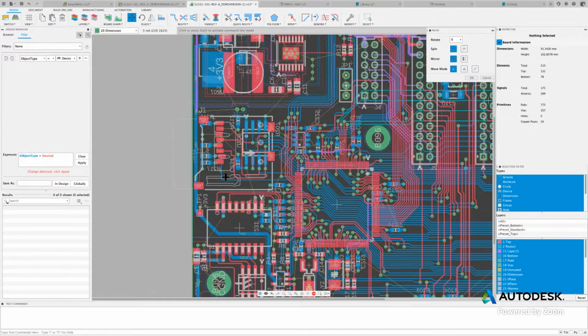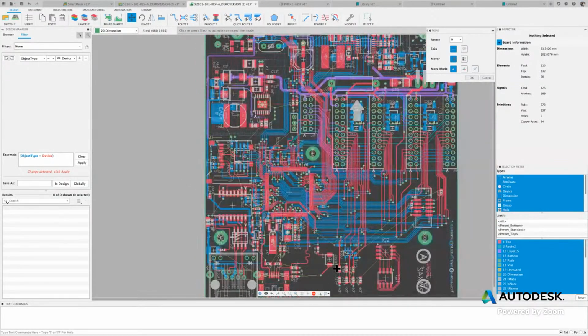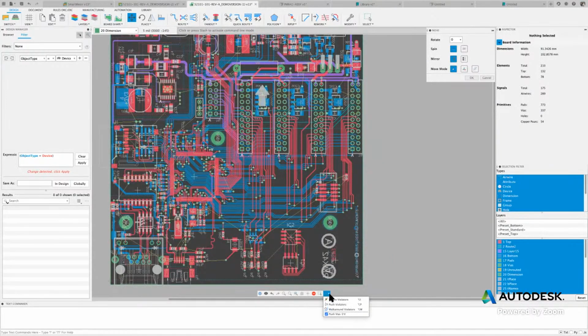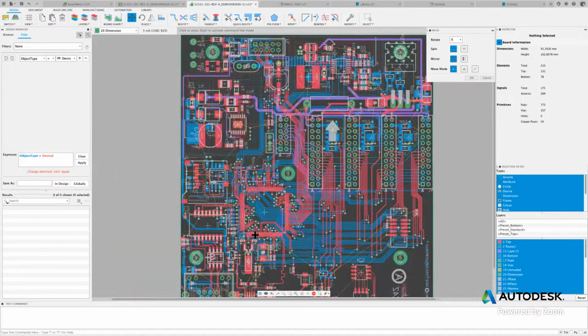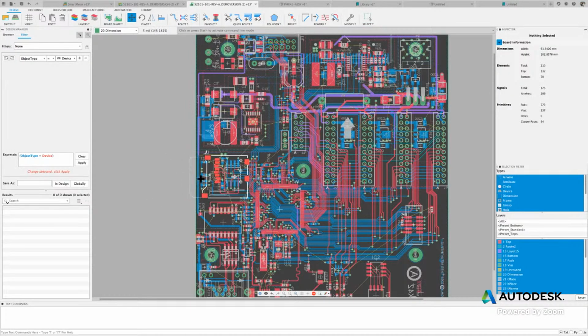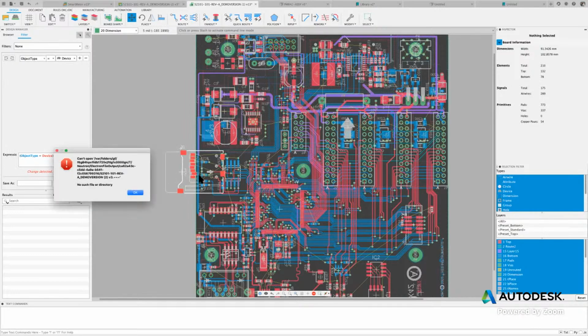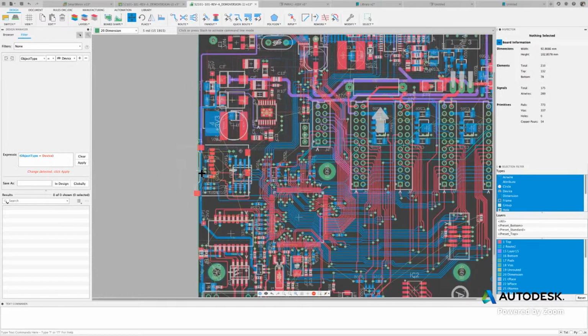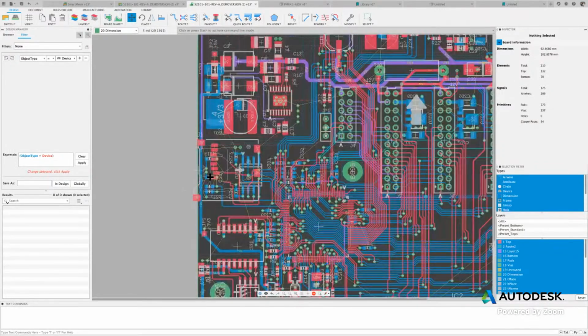Now, I could change that environment, and I could change it that way it ignores violations. So I'll click here where it says ignore violations, and I'll go ahead and move that same component. That way you could notice the behavior difference. Okay, so let's go ahead and grab the component right here. And as you can see, it's moving now freely because I've told it to ignore. But what happens when I use this environment? Let me get a little closer. That way you can see what's going on.